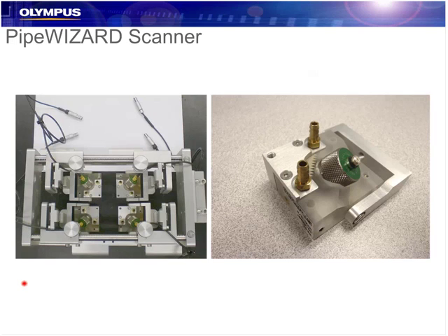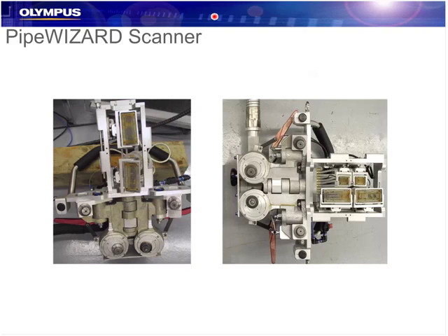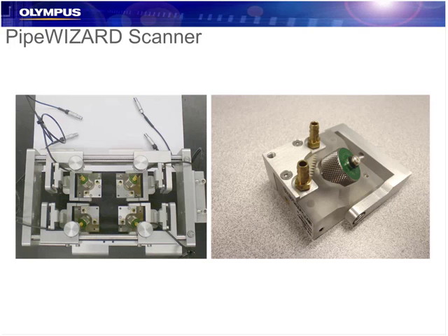So here we look at a transverse module. So if I go back just one slide, here is a connection. We'll be able to connect another module onto the unit, expanding the footprint of it. And now if we need to shoot across the weld, we often use just conventional ultrasonic transducers to look for things like transverse cracking or transverse defects if there's a requirement for that. So it is adaptable to different ultrasonic techniques.